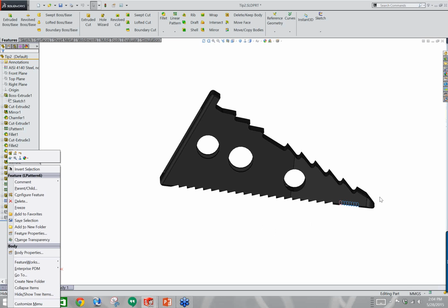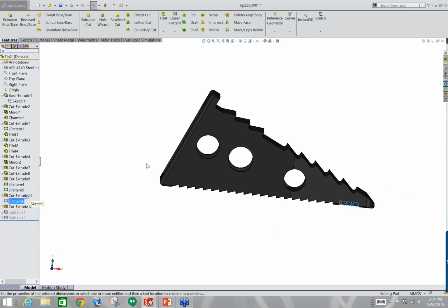All right. Any other questions? Yes, as Randy pointed out, you could do a sketch pattern instead, which will actually have better performance than a feature pattern. But in this particular case, it would. It might not in all cases. Sketch patterns can be really complex as well, and so you might have to play around with it a little bit and see what works best in the particular case that you're working on.